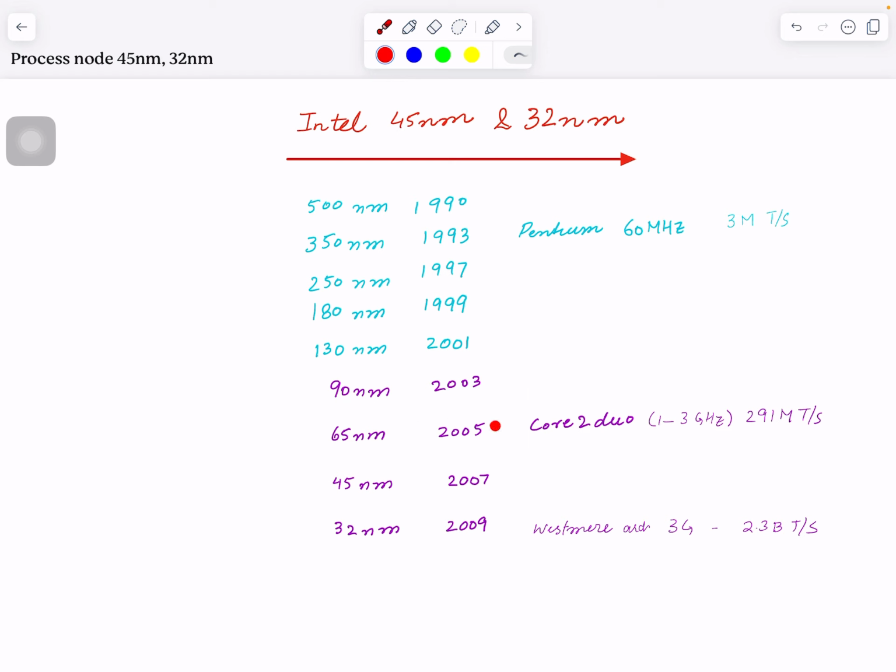Okay, and then we started seeing that with 90 nanometer, which we discussed last time, and then 65 nanometer, new technology came. Here strain engineering came. The first generation of strain came. Now that was a new thing, which was not done before. And from there, transistor gate length started slowing down, and we have seen that the gate oxide thickness started slowing down.